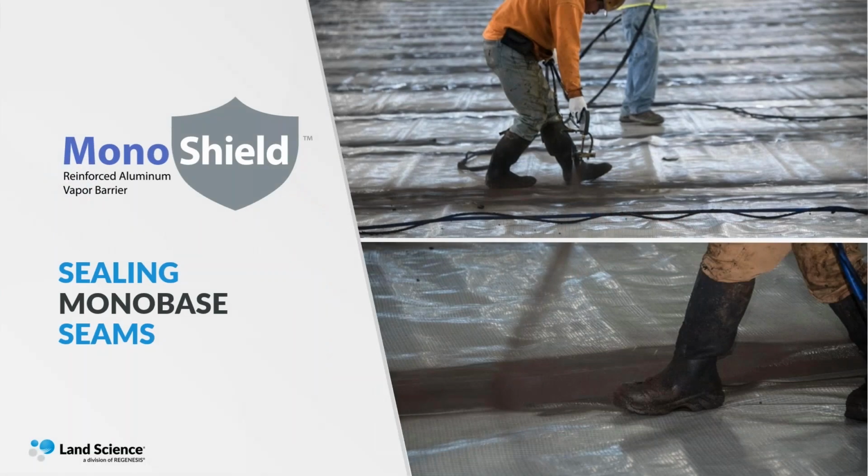So as I mentioned, you can see here, these are pictures of the seams being sprayed. They're sprayed at a 6-inch overlap and a 30 mil spray and then a 60 mil cap over the top of that, creating that seamless effect. But as you can see here, it's still just a single layer system.